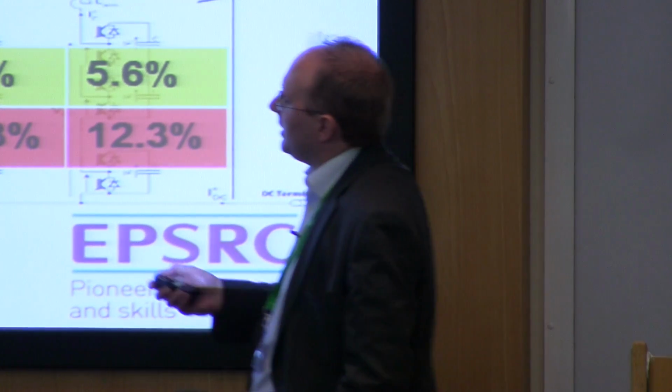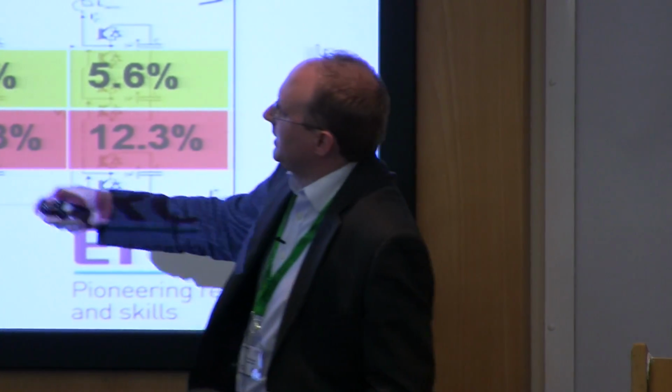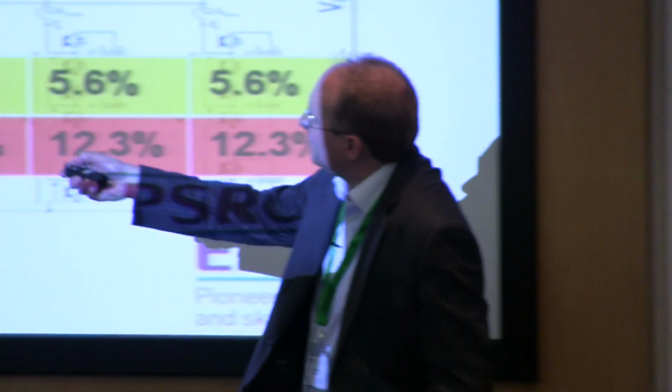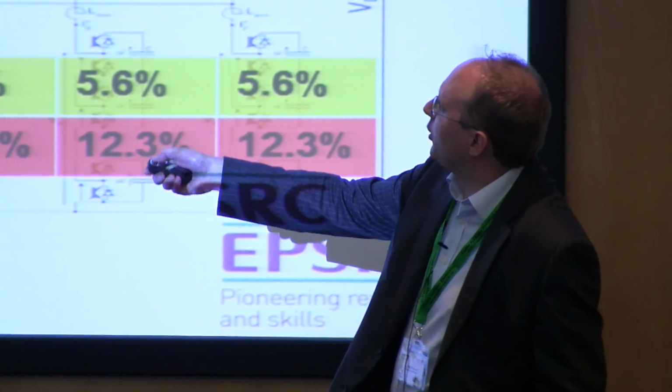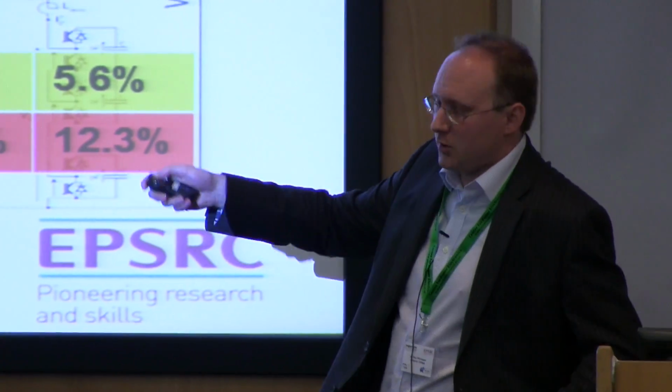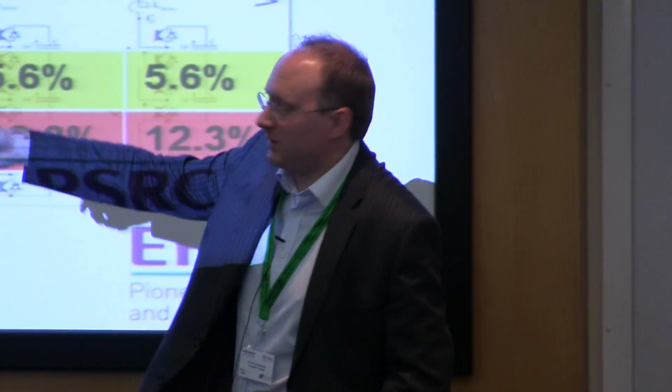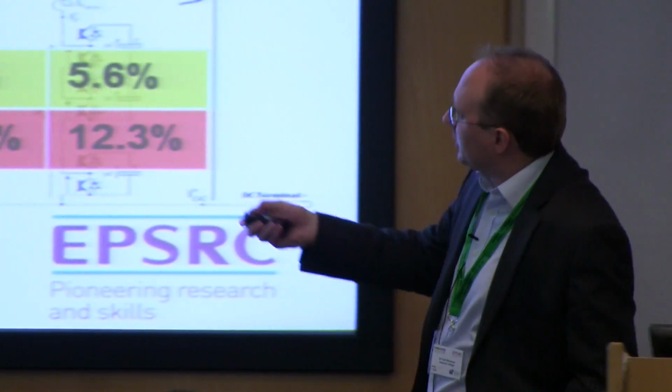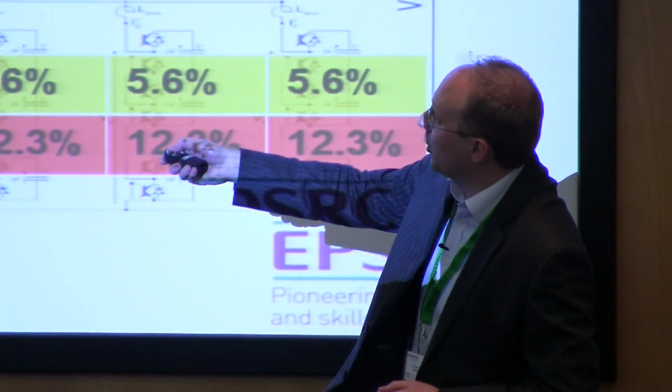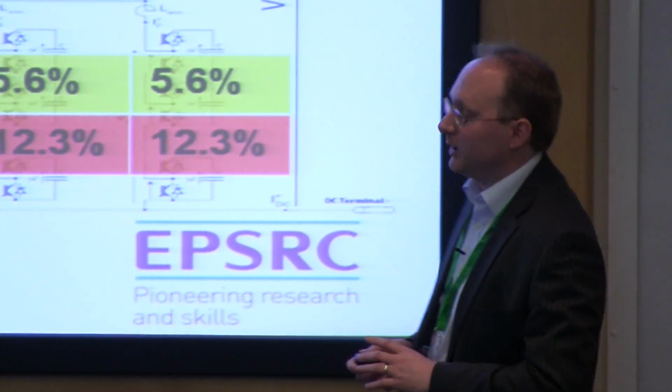And that's just simply because if you're mainly dealing with real power, of course, the peak of the current tends to happen at the point when these cells are not subtracting voltage from the DC link. And consequently, you end up with more 0 volts switched in, and therefore you get more current paths through the lower devices than the upper devices.